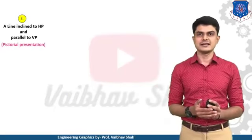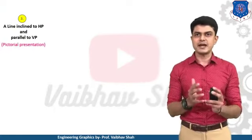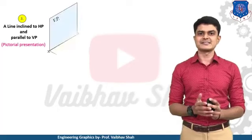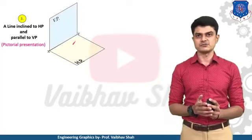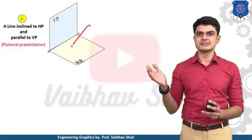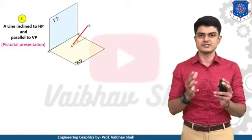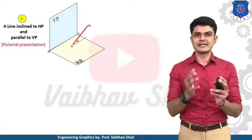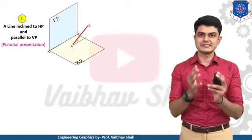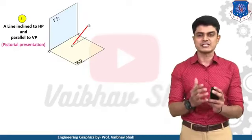So let us see what the third case is. The line is inclined to HP but it is parallel to VP. So let us understand this case by a pictorial representation. So we will be taking one line. As you can see, this line is parallel to VP, but it is inclined at some angle with your HP, as you can see. So this is the inclination. Let us suppose we take the inclination with respect to HP as theta, then this line is now theta degrees inclined with your HP.